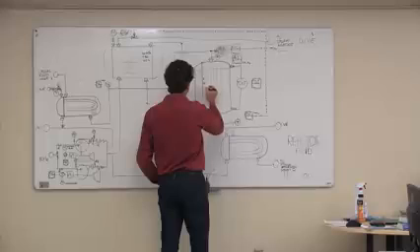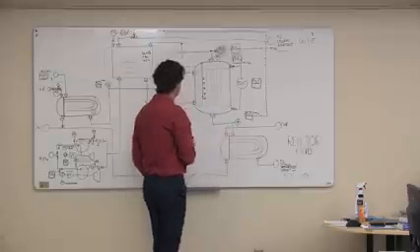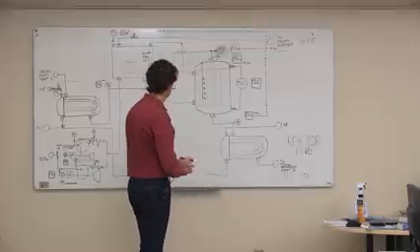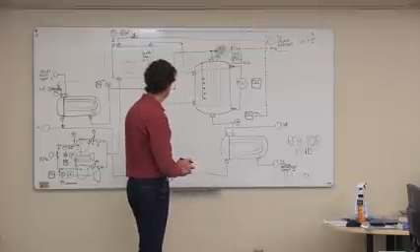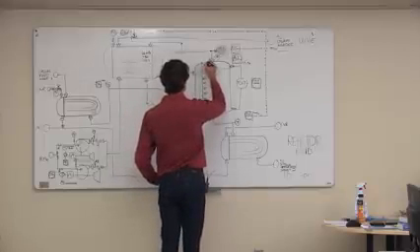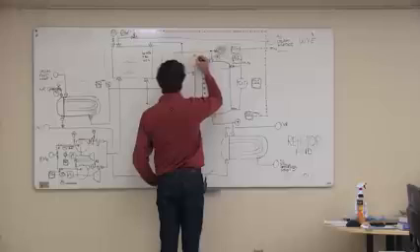Problem is the temperature element, depending on how big the tubes are themselves, the actual temperature thermal well or whatever we're going to use to do that could kind of interfere with some of the flow rates, so it may not be super accurate, and the temperature elements are probably going to fail at some point in time as well. So, but anyway, you might want to try and do it anyway.